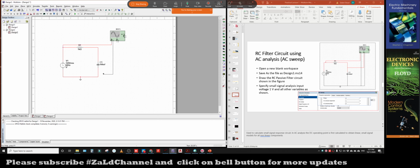Make sure that when we use the oscilloscope, the black or negative one should always be connected to the ground. So for this case, the negative one I will connect to the ground, which is the common terminal of the ground.